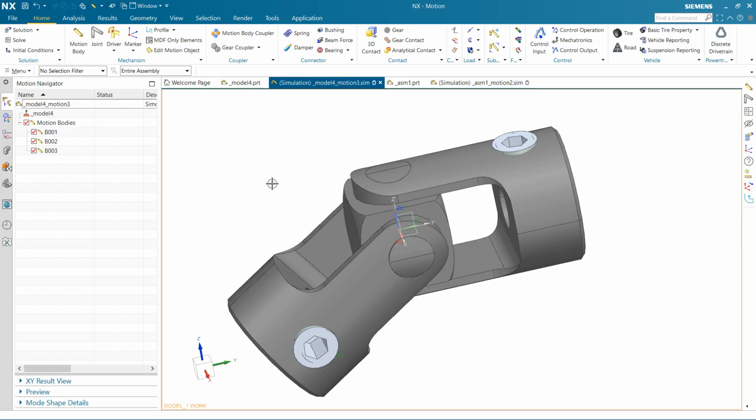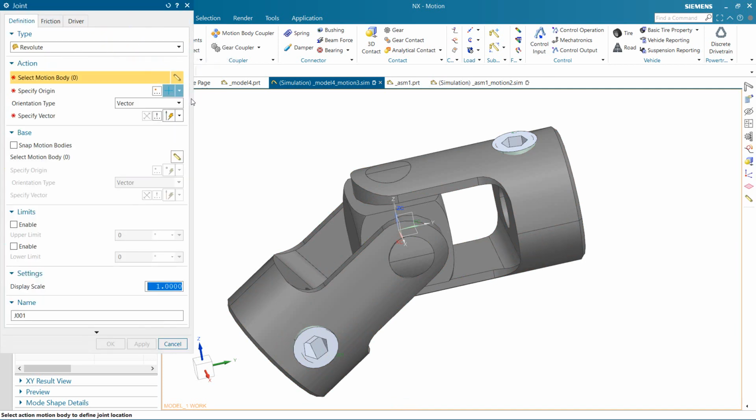The thing I want to do here is create the revolute joint for this object, this one here, as well as this thing, and also the spinning object here. Okay, so let's try it. Create a revolute joint for this one. Actually, we will create two of them. For this one, you just create a base body.